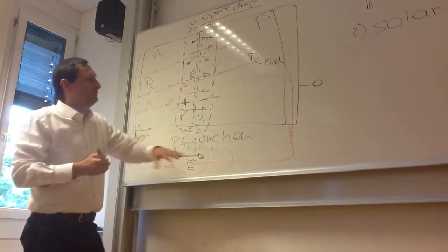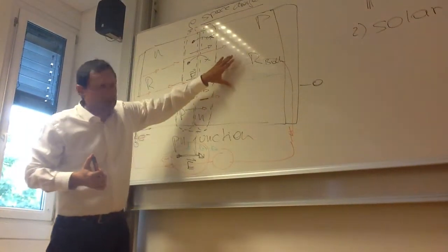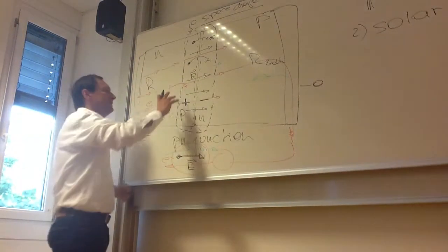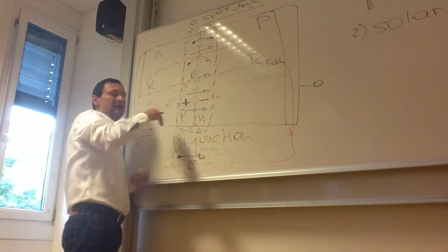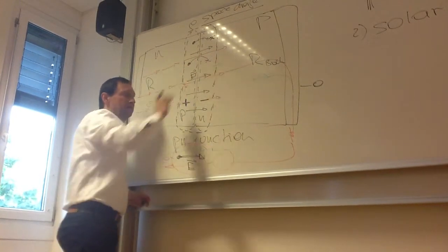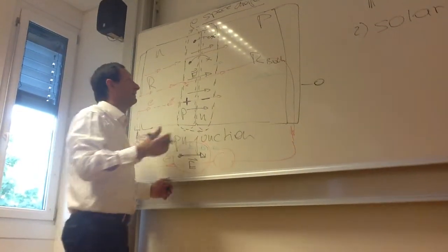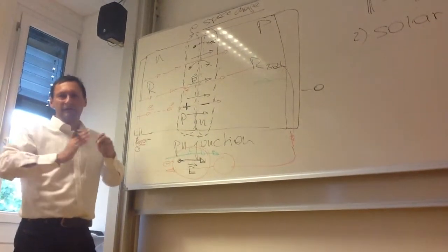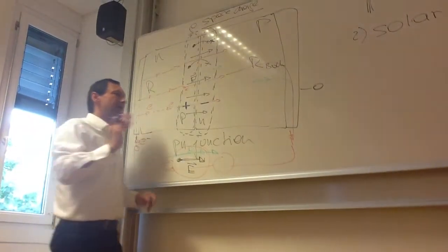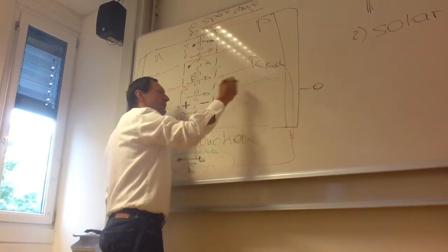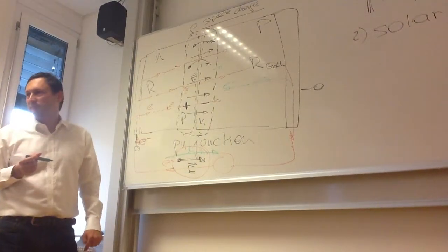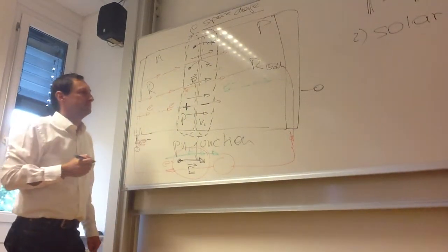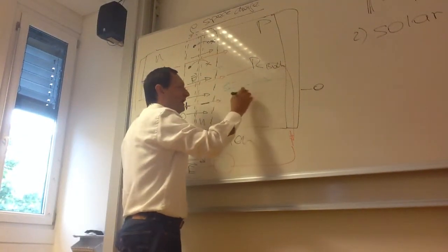Because if we are pumping in electrons here, then from the other side the electrons are extracted. So this positive charge here gets even bigger, and the negative charge on this side even gets bigger. That means our space charge area widens a little bit, but nevertheless it's not possible for the electrons to move in that way. It's not possible for the electrons to get across the junction. So in the green direction there is no current flow.